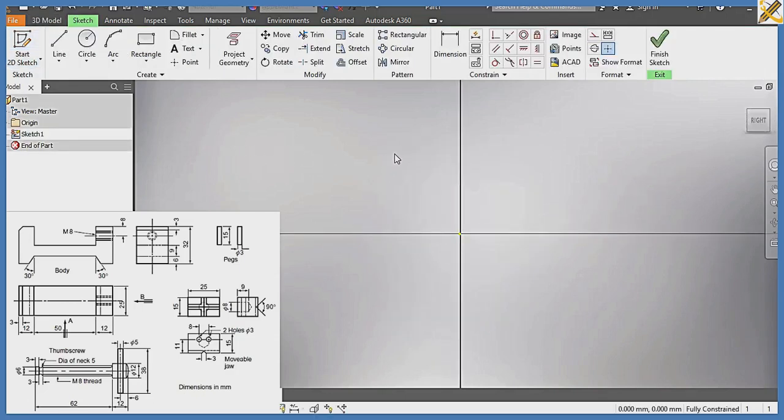I'm going to start this drawing with the body. So that I won't give myself unnecessary headache, it is better for me to go with the front view in developing this. So let's start. Looking at the drawing, I'm going to pick a rectangle. The total height is 32, while the total span is 50 plus 24, that's 74. Then I press enter.